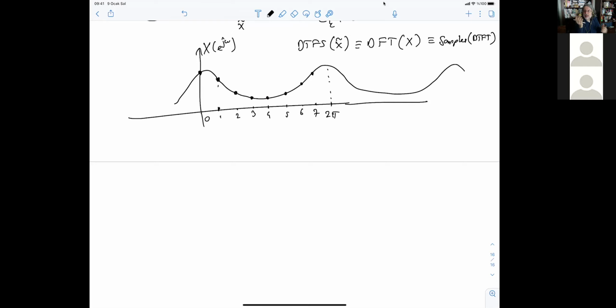Every complex value will have a real and an imaginary part. So it's twice the data that you're looking for. It is expanded. But only half of the data is enough for you to render the discrete Fourier transform, because it is conjugate symmetric. The right-hand side of this part and the left-hand side of this part are conjugate symmetric to one another. They are complex. So this part is the complex conjugate of this part. So if I cut from the middle, the right-hand side can be reconstructed.